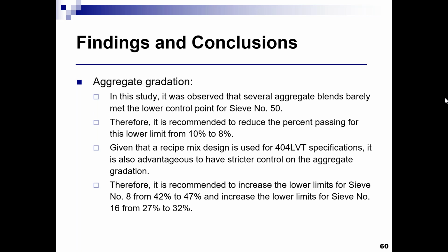The transverse cracking shown in your photos appear to be reflective cracking commonly coming through the existing road base. You may want to core these locations and see if the crack continues all the way through the lower asphalt layers. That's actually a very good comment. And I think to add to your comment,